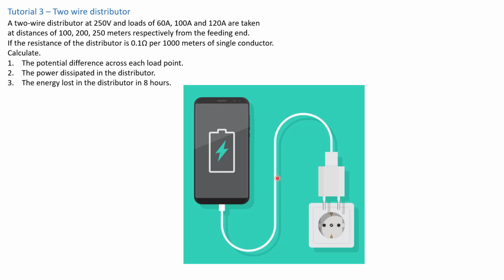And that voltage drop along the cable will result in your battery not getting the appropriate voltage to charge. Because if this charger was configured to charge at 5 volts, now you are losing about 1 volt because of a bad cable. So you're going to be getting 4 volts here, and that's not a good condition to charge your battery.